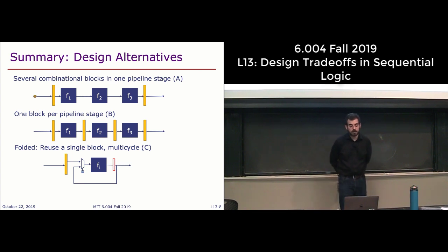You can see that each input has to go through all the blocks, and so that is going to set the clock cycle time here, right? So we are not overlapping inputs. On each cycle, this circuit processes a single input end to end.